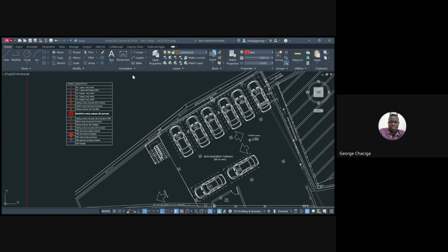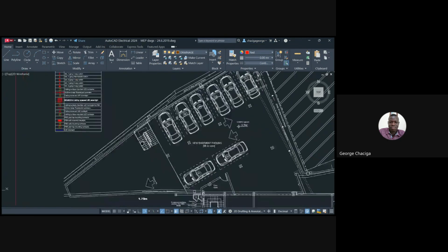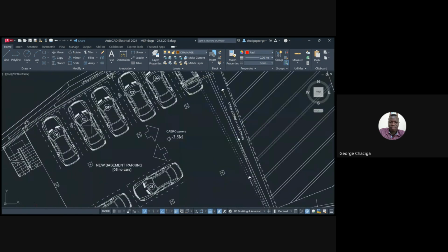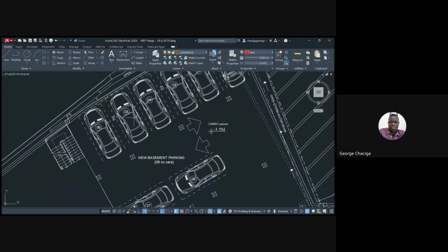Today we're going to see how we're designing that room strictly. There are some that follow the principle of the height of the room that you're lighting with a spacing, whereby they can specify that if the height of the room is, let me say, 3 meters, you're going to space the lights by 1.5 of that 3 meters.